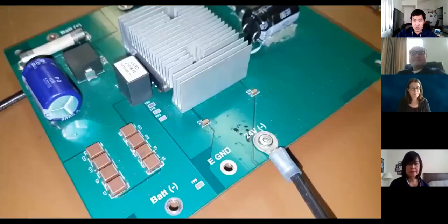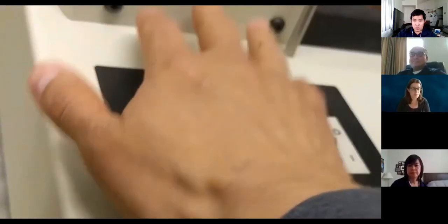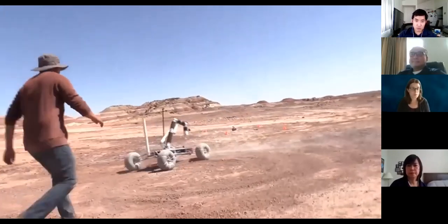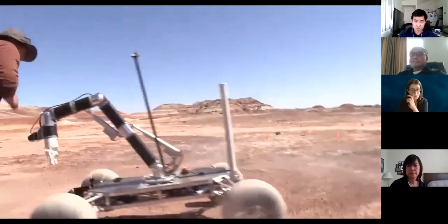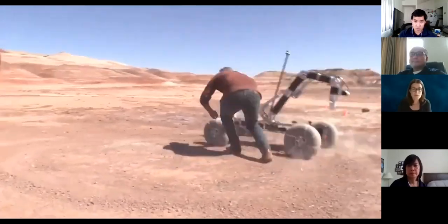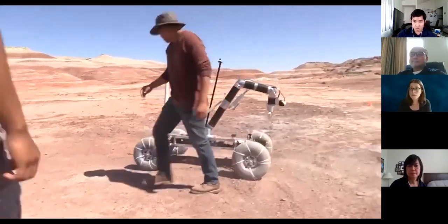In addition, we have a physical kill switch with dual circuit control using an internal solenoid. This allows us to physically cut all power to the rover, as well as send a remote command to depower the mobility system in the event of an undesired movement.